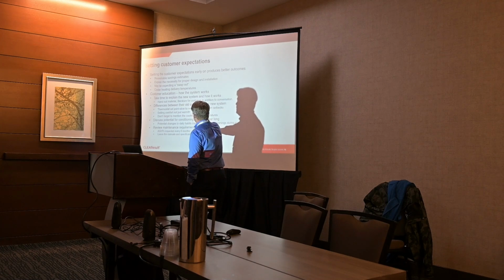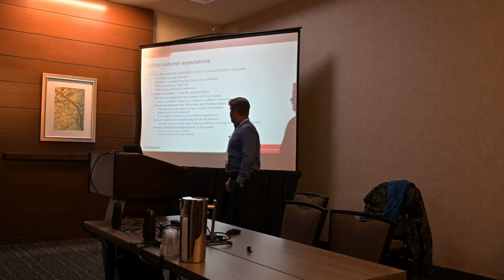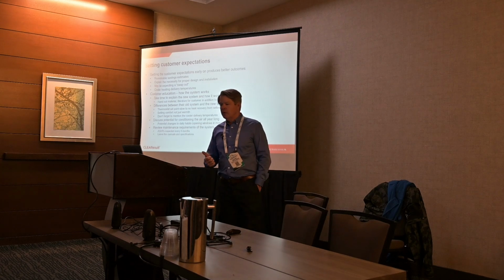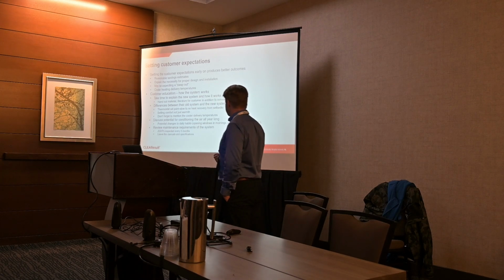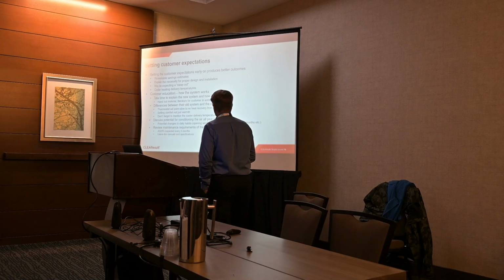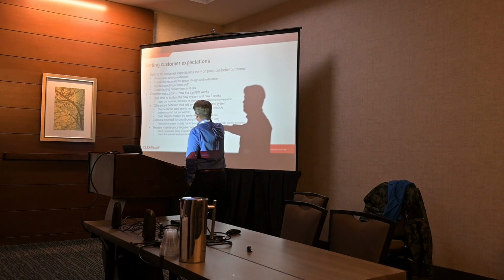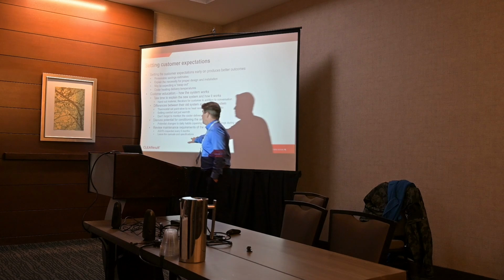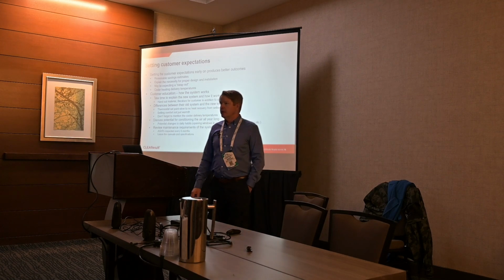Okay, and then also review the maintenance requirements of the system. Gas systems, typically, you can service them every 2 years. Oil, they say once every year. Heat pumps, probably every 6 months, whenever you change season. You want to have somebody take a look at it, okay? And then make sure that all the manuals, specifications, rebate information, all that sort of stuff stays with the customer.